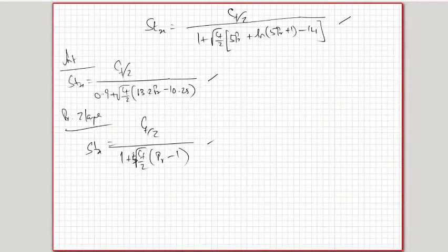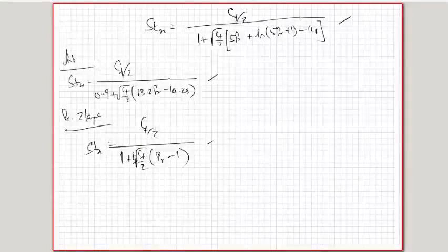Okay, so that brings us to the close of the discussion that I wanted to have on the simplified, more classical methods of the turbulent boundary layer profiles. And we find that the discussion that we have had so far shows that by multiple methods we arrive at quite similar expressions depending on the extent of approximations involved.